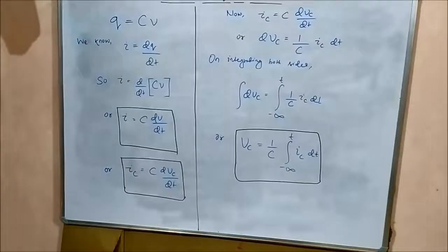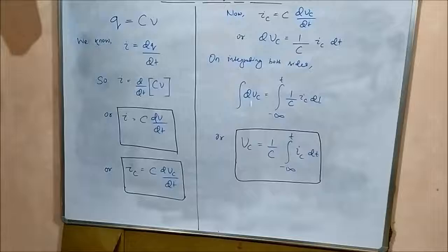In a resistor, the voltage drop goes from the maximum voltage to 0 as soon as the current through the resistor is 0. But inductors and capacitors are not like that. The voltage across the capacitor will not abruptly change from the stored value to 0 instantaneously. It will take some time to discharge and lower its voltage value.